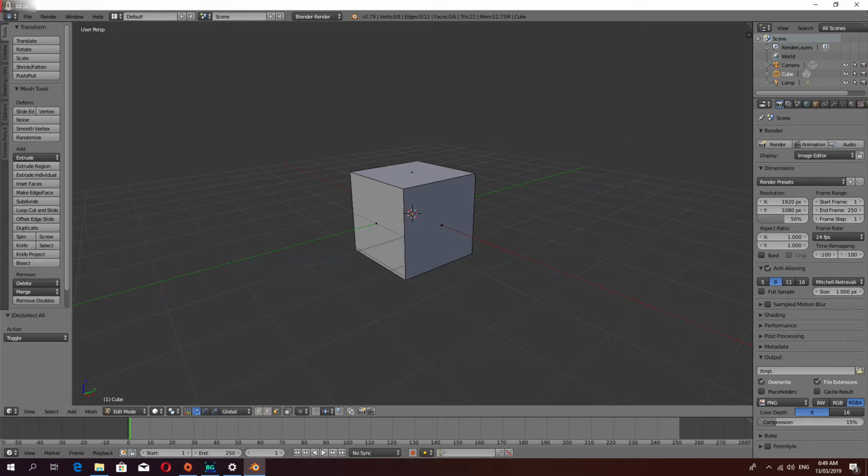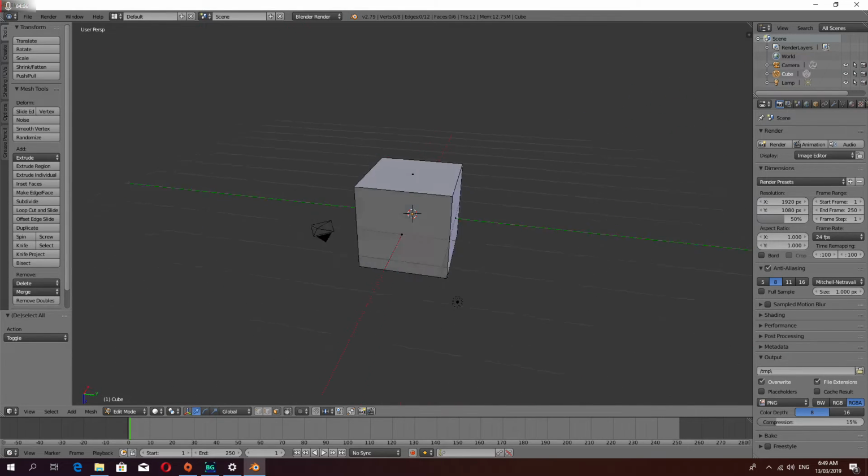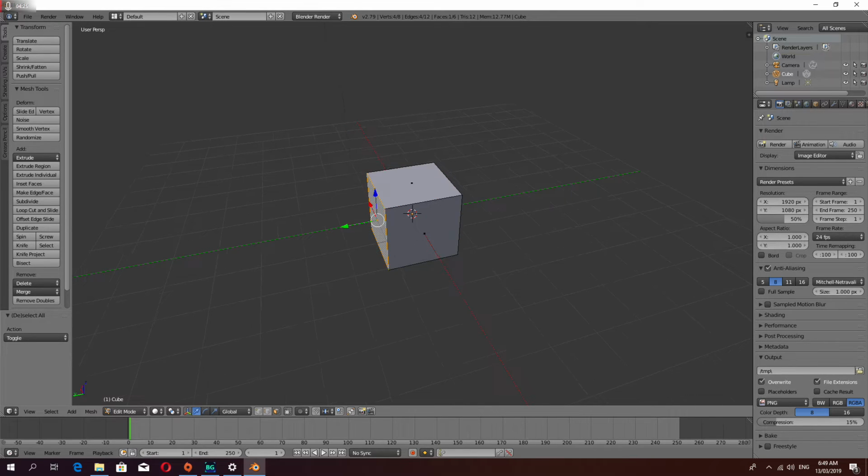Down in the bottom left corner, you want to be making sure that when you're working with something, you've got the Z-axis pointing up. Otherwise, you're working upside down. And it's not a big deal. I mean, if you happen to build the whole model upside down, it's very simple to just rotate it up the right way. But some of the controls will be confusing and reversed. So that is rotation. So we can select.